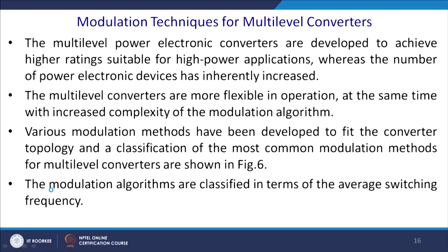Now, let us go into the multi-level modulation technique for the multi-level inverter. You have more than 2 levels. Multi-level inverter power electronics converters are developed to achieve higher ratings suitable for high power application, whereas the number of power electronics devices is increased. That is one of the disadvantages you get, but the power rating of these devices is lower.